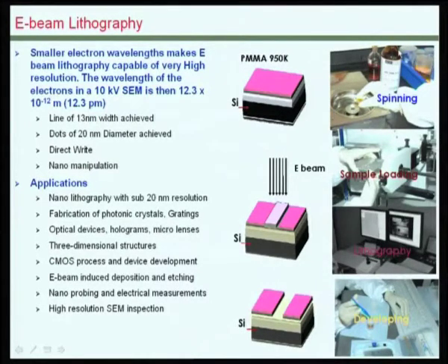So, the process steps are somewhat similar. You spin coat the PMMA resist, and then the sample is loaded onto the equipment, and the patterns are transferred using e-beam lithography, and then it is developed and etched. So, it has various applications.